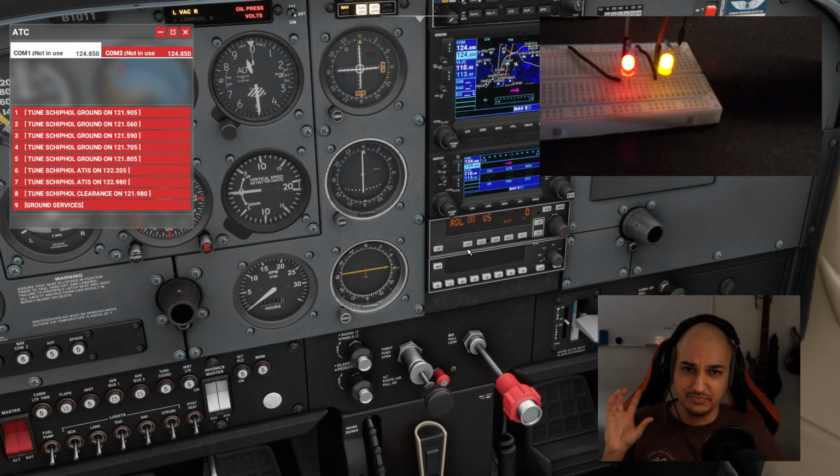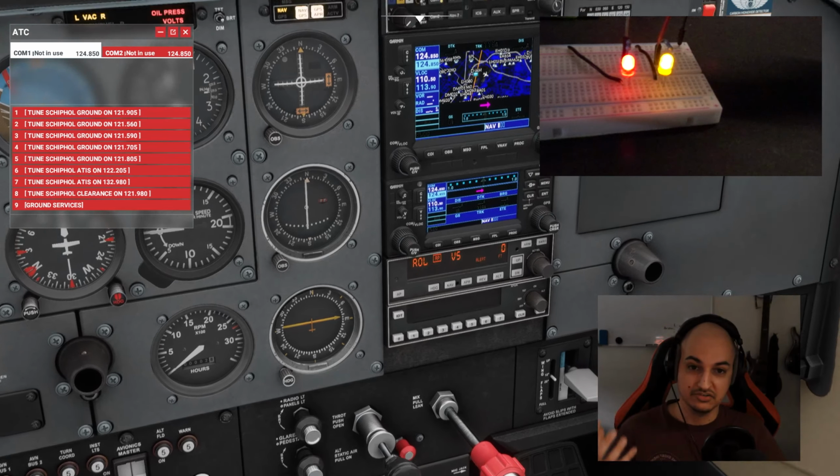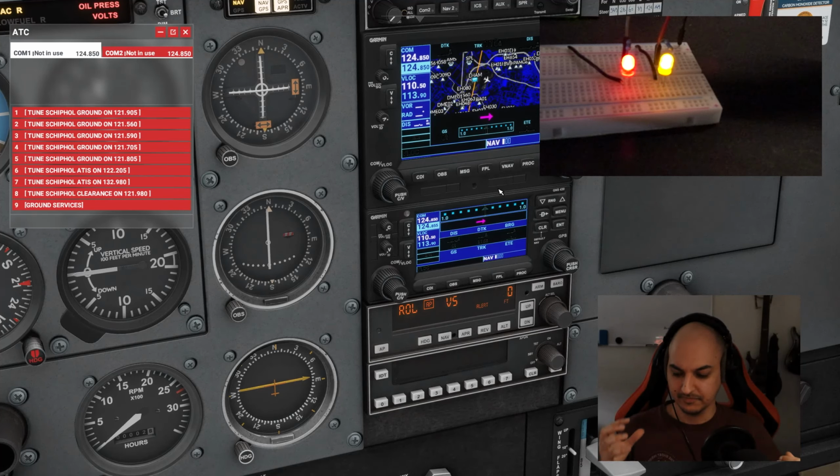I'm working on some pre-made alarms in the library as well. That's going to be linked to the G1000, for instance, where it says low pressure or something. The downside is those warnings exist in the G1000, but to get them, I actually have to read the actual manual of airplanes to see at which altitude or pressure value it turns on, and then send a command to your Arduino. So that is something that's coming up. It's going to be quite some work to read through all of that to see all the cutoff points for different planes, and how to handle that as well. But that's more for the future.